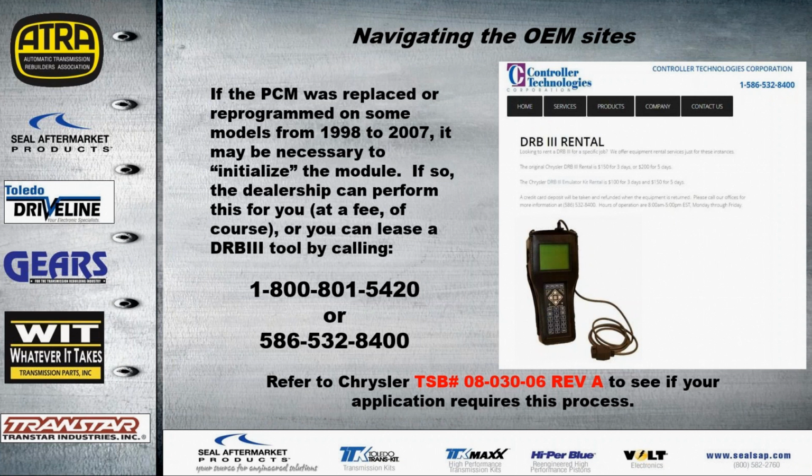Now, in the case of some Chrysler applications from 1998 to 2007, it might be necessary to initialize the powertrain control module if the powertrain control module was replaced or reprogrammed. In this event, you would have to either take it to the dealership, which will do it for a fee, of course, or you can lease a DRB3 tool by calling the Mopar direct number, which would be a 1-800 number, or Controller Technologies. They have the same service available.